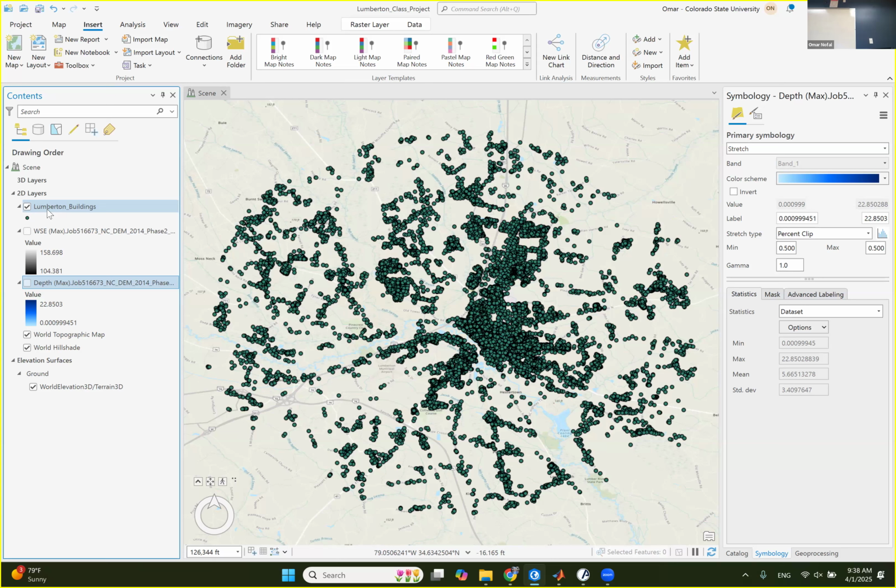So if you remember the mapping algorithm, when I gave you a MATLAB code called mapping. You are just gonna replace the file that you have for Nueces County with the new shape file, run the MATLAB code, and it's gonna give you a mapped shape file for these buildings. Do you remember we had an algorithm that adds a field called the building archetype, and in this field, you put archetype 1, 2, 3 up to 15. All right. So once you are done with this step, you are gonna use a MATLAB code.